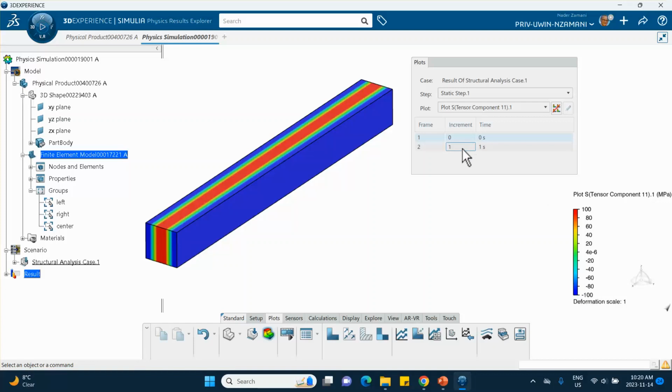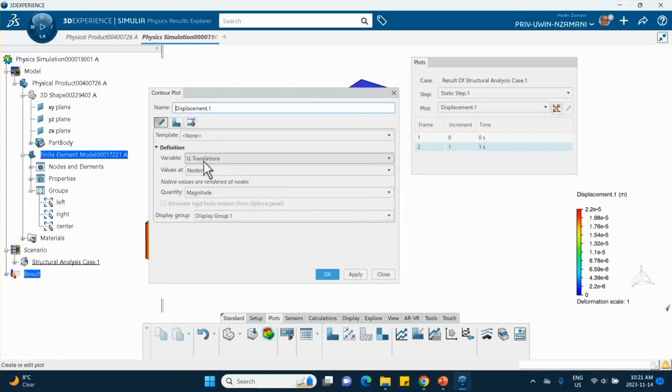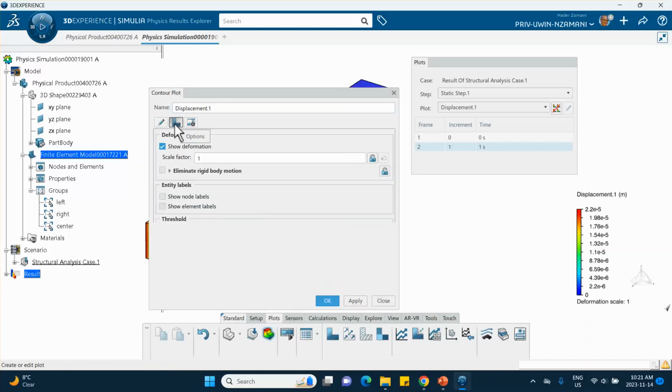But after they deform, the object deforms because of the initial stresses, of course, things will change a little bit and look like that. If you look at the plot of this deflection, it should be only axial deflection pretty much. So if you go to the displacement, and if you increase the scale, because this is a unit scale, so let's go to the middle tab, make this thing 100.